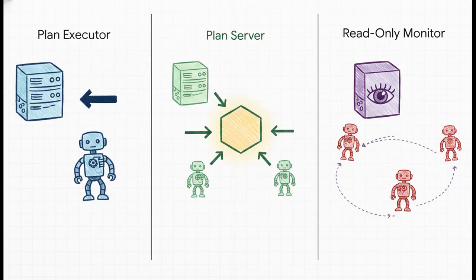And finally, number three, read-only integration. This is super low risk. Your legacy system simply monitors the VDA state telemetry to see where the other robots are, adjusting its own routes to avoid those swap deadlocks without giving up primary control.